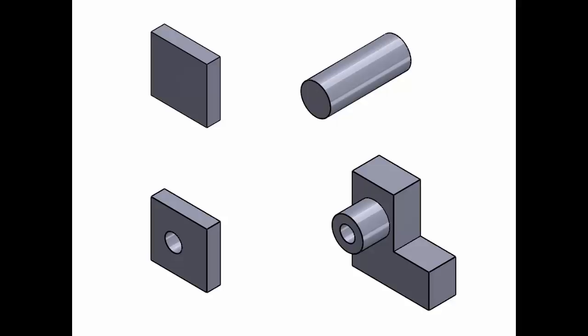It's important to understand that you can sketch on origin planes, part faces, and user-created planes. Remember, extrude requires you to create the shape and then give it a thickness.